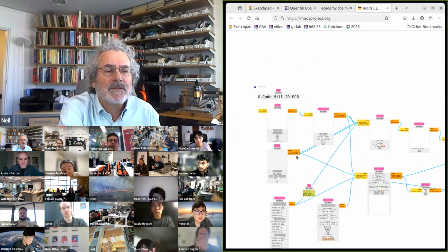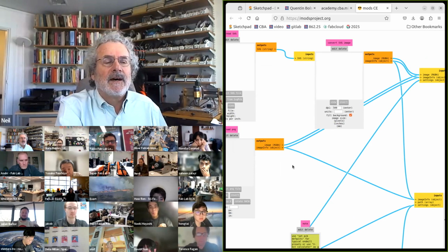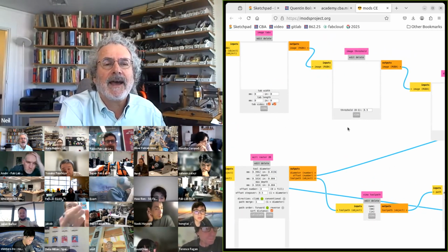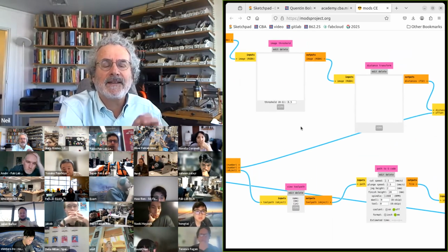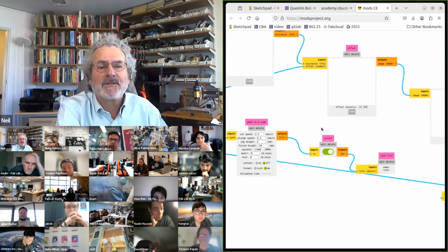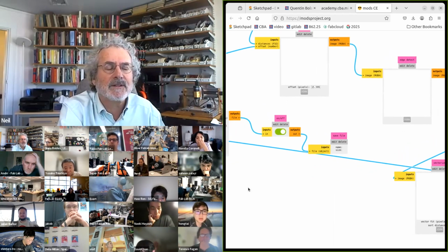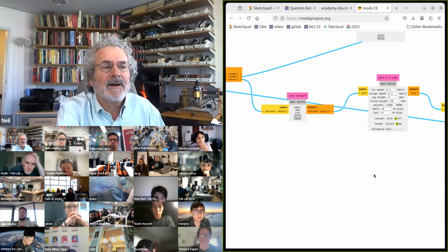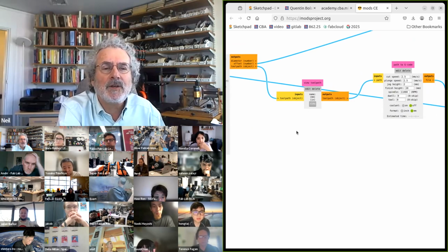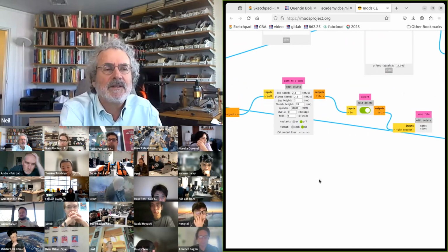If we go through all the steps now, this reads an image in, this adds tabs, this finds the distance of the edges, this offsets for the tool diameter, this finds the edges, this turns them into vectors, then this sends it back to the coordinator, then the coordinator accumulates those, this converts it to a G code, and then this sends it to the machine.